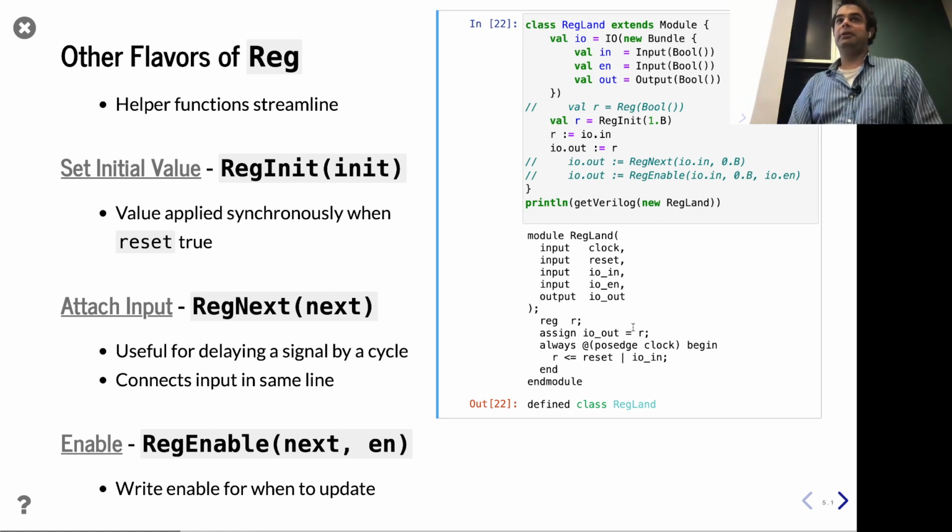Of course, we could change this to be a 1, and then this register resets to 1, and the code generator is being a little clever here. It realizes that if reset is 1, you're resetting it to 1, well, then you could just actually use reset directly here. It's a little clever logic trick the tool did automatically, but it's the same hardware, or same function, I should say.